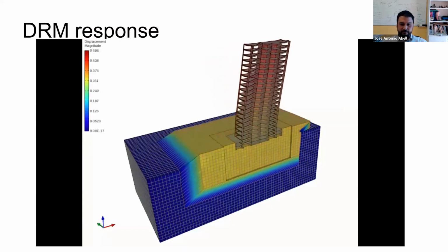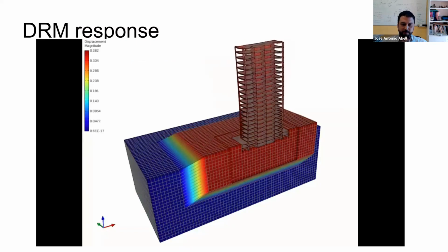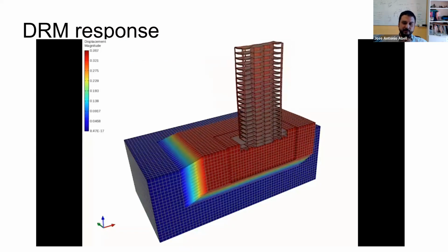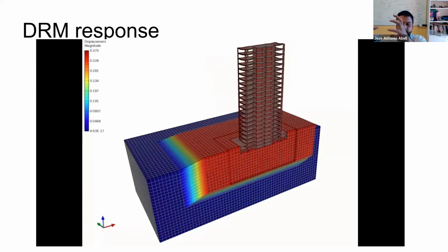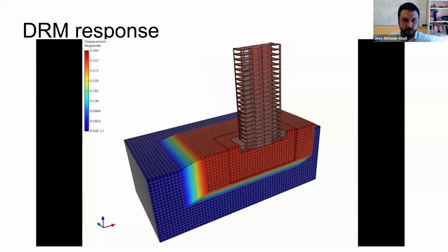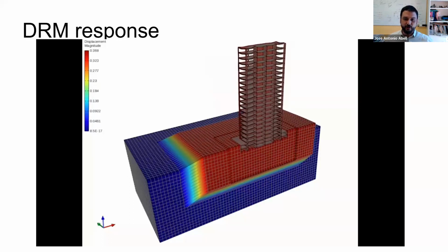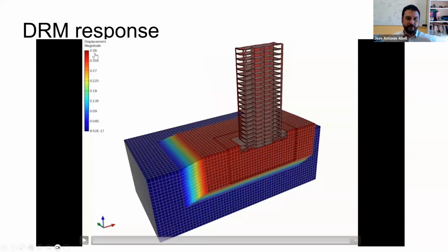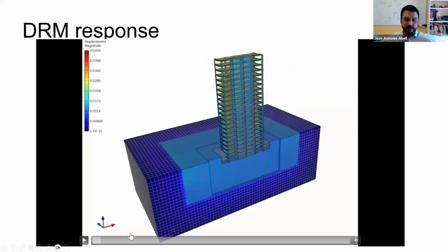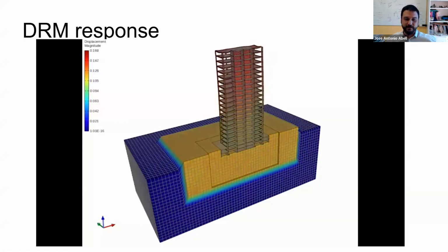Some people are very disconcerted by what these simulations look like with that block drifting. You have to remember that inside the DRM box, that's your physical place, and it's moving along because these are realistic simulations. So they do consider that the soil moves, and there's a permanent offset due to the earthquake. The earthquake moved soil around 1.7 meters or something, and this place on Earth is moving like 36 centimeters towards some direction. I forget what the orientation is right now, but there's a permanent offset after this. Another thing that is interesting is you can see at the beginning how the motions propagate up into the building.